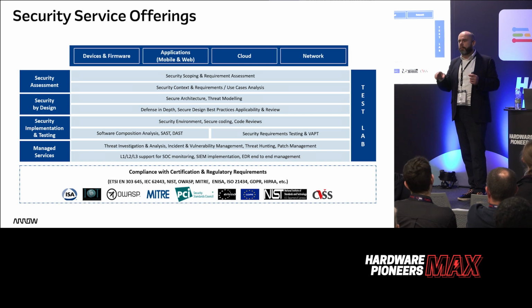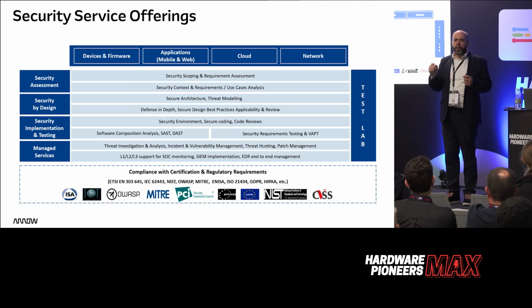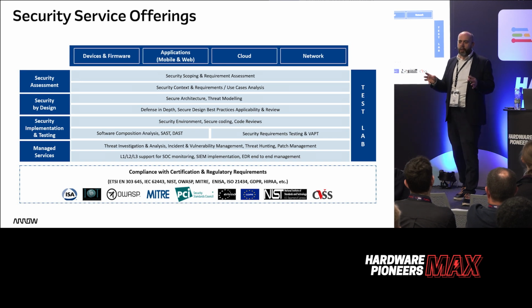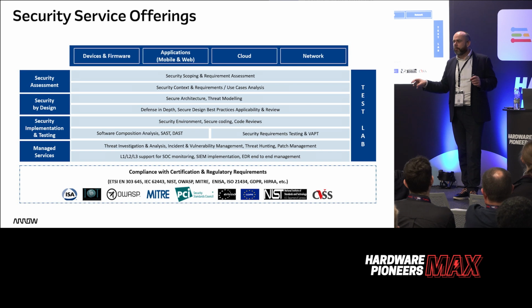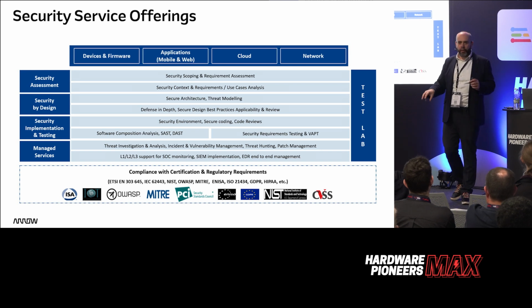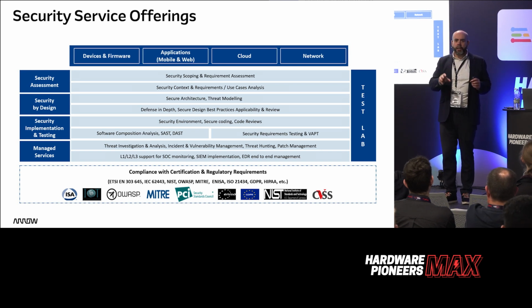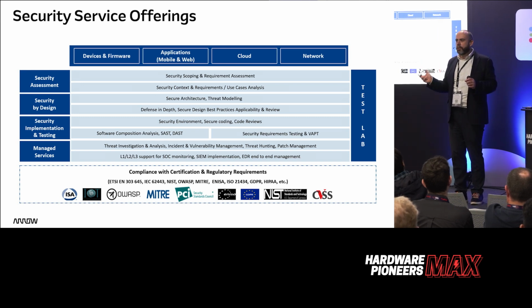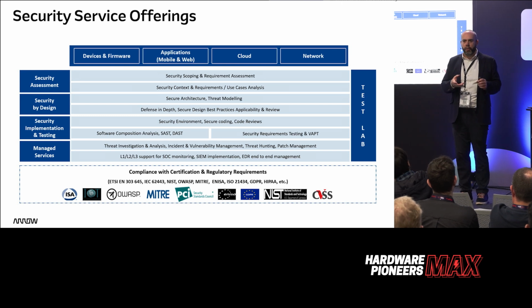But the chip itself isn't secure unless you use the security elements in it. I know that sounds obvious, but it's worth repeating because you can't buy security. You have to design security. You can buy processors and FPGAs that have security features, but you have to understand and use those features correctly for your product to be secure.